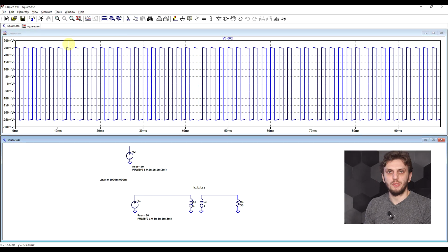Now, since we're talking about AC signals, they will be referenced around 0. So that's why we're not getting the initial signal from 0 to 1 volt. First of all, we're getting half of it because we're matching the impedances, so 50 ohms on the signal source, 50 ohms on the load. We should only be getting half of the initial 1 volt, so half a volt. But because we're only transmitting the AC component, everything is referenced around 0 this time, so plus minus 250 millivolts.